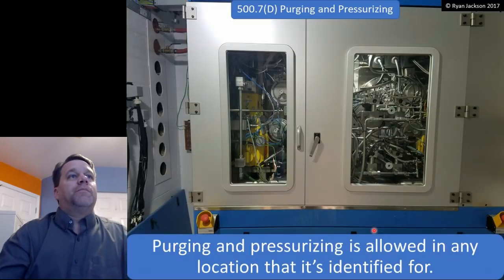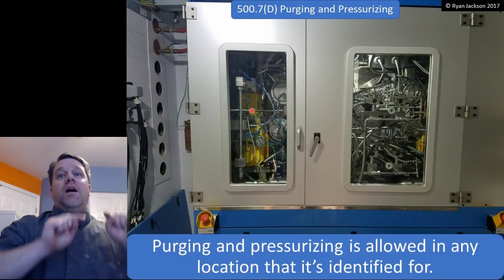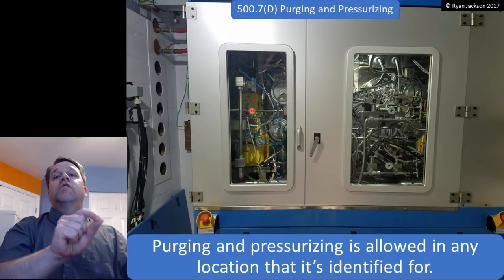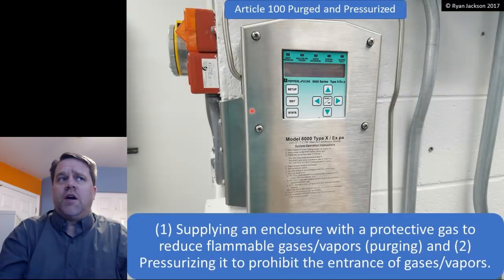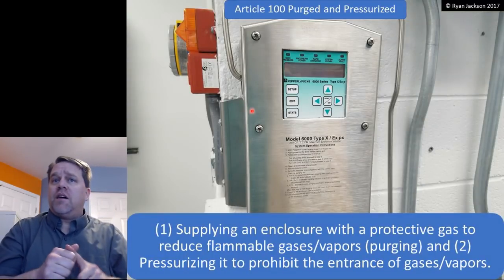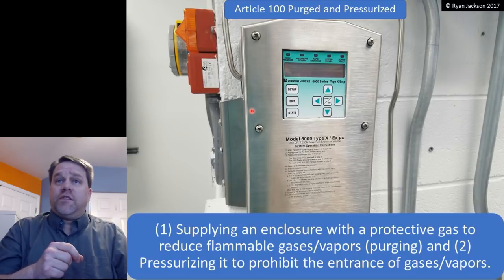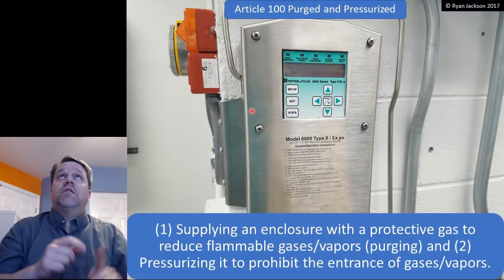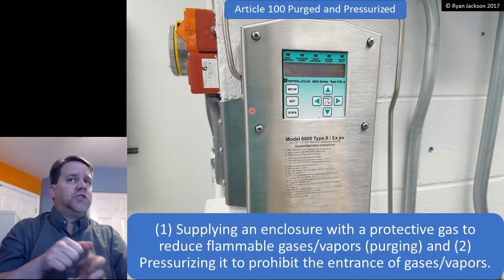So let's go back here. Step one, I purge all the bad stuff out of the equipment. Step two, I keep it pressurized so that the bad stuff can't enter the equipment, right? So that's purging and pressurizing. Purging and pressurizing comes in three different flavors: type X, type Y, and type Z. And off the top of my head, type X allows you to go from a Division 1 to a Division 2.